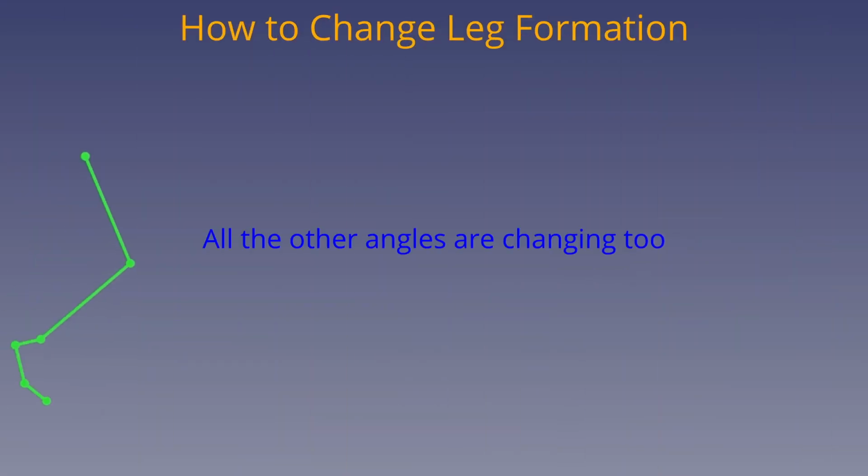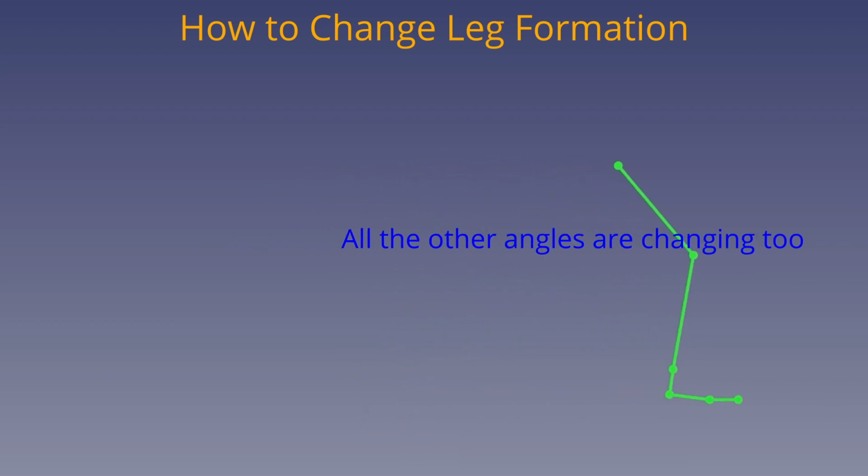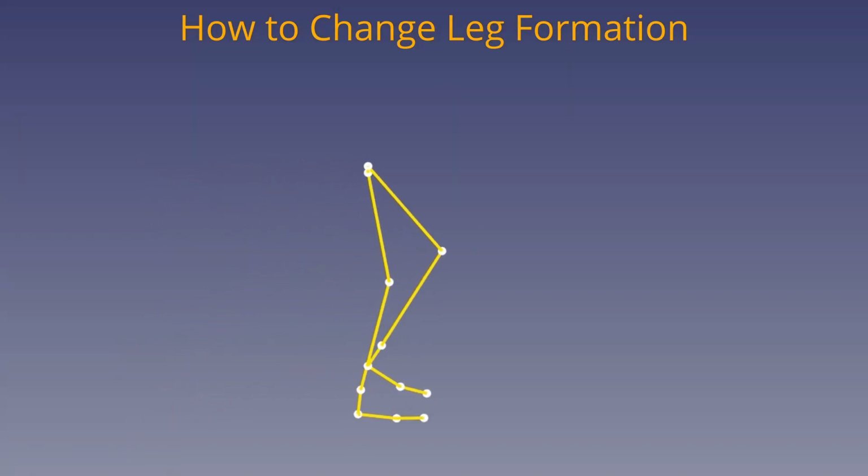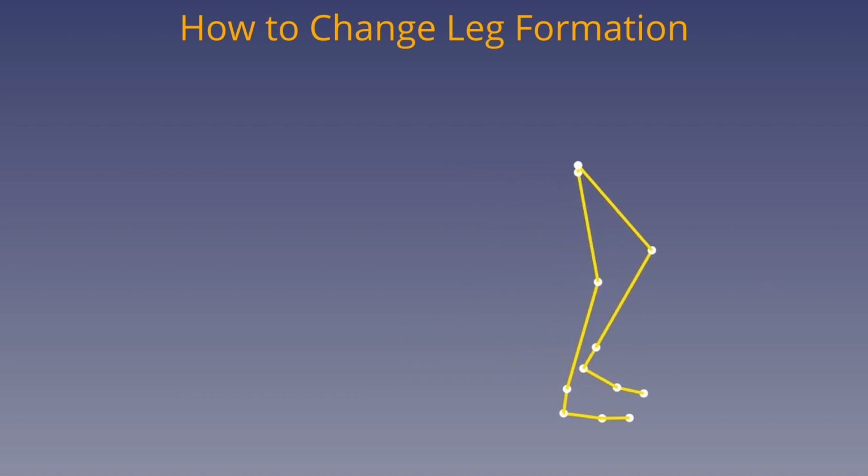In this way, by setting up all the other necessary equations for the other values, such as the foot angle value from the ground, and applying them to the sketch constraints, I could have the whole leg formation change simultaneously according to the reference value changes.